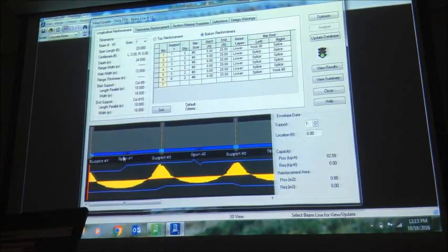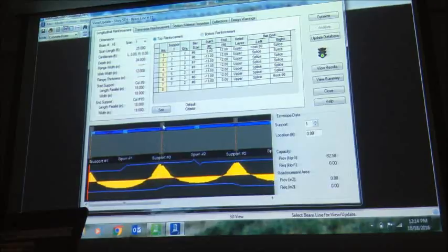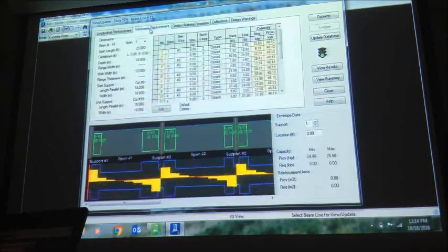Okay. And look at the spans. This is the moment, this is the reinforcement. This is the moment, this is the reinforcement. Again, top, this is the moment, this is the reinforcement. And also transverse: 5 number 3 at 9 inch on centers, 9 number 3 at 9 inch centers, 7 number 3 at 9 inch centers.